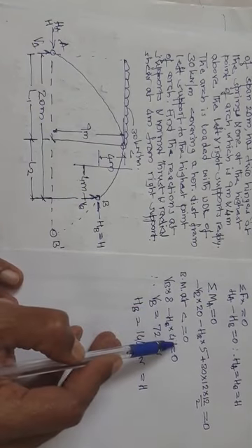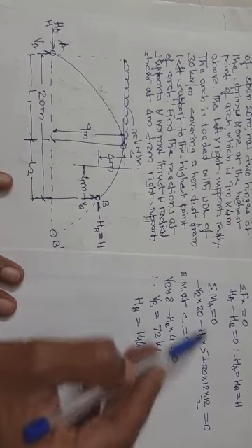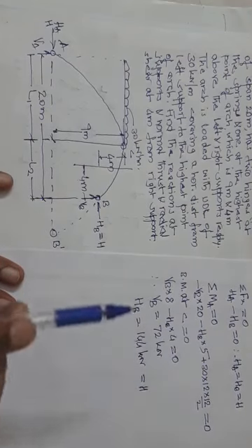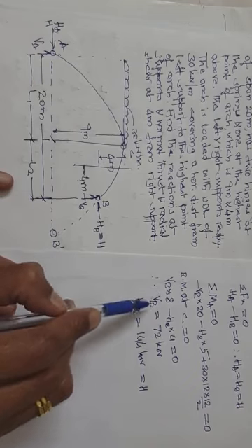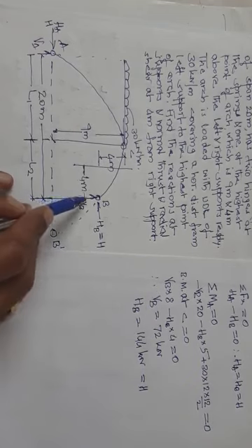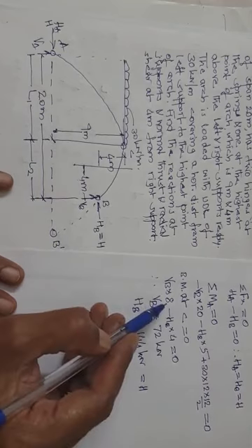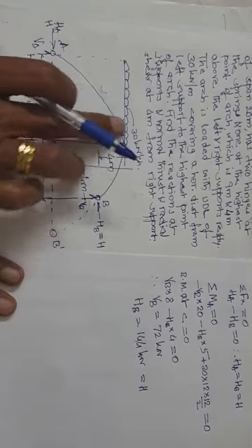If you write the bending moment at C, considering the left side, for bending moment, left side anti-clockwise is positive and clockwise is negative. For writing sigma MA, that is static equilibrium, you can take anti-clockwise as minus and clockwise as plus, or the reverse can also be taken. For bending moment, on the right side anti-clockwise is positive, hence this is VB into L2. What is L2 now? This is 8 meter. VB into 8, here you are writing the bending moment at C.